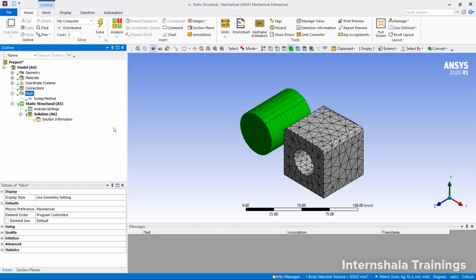And remember, the sweep meshing technique can be applied to generate hexahedral elements on a few of the objects, especially when you are using mechanical pins to join two objects in an assembly structure. There might be some critical areas. There you might use this sweepable mesh technique and create hexahedrons on that pin and on that contact area also. In such cases, this particular sweep mesh can be applicable. So once we have finished the overall view of sweep meshing, we'll do some manual selection also.